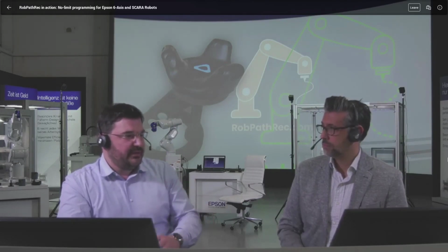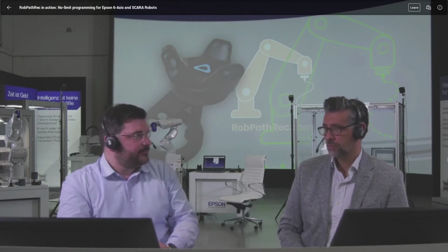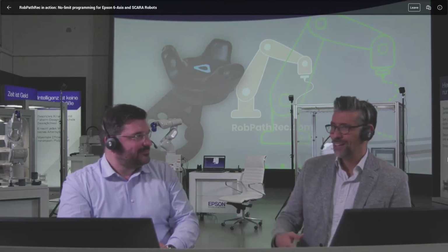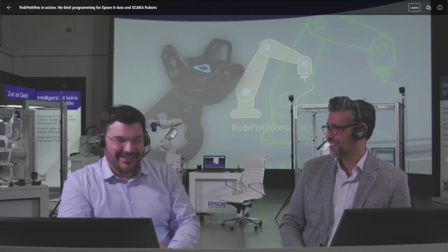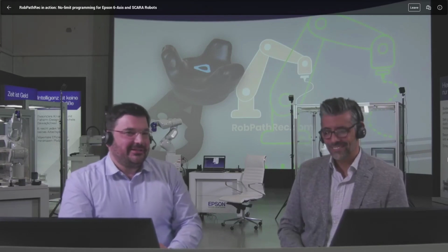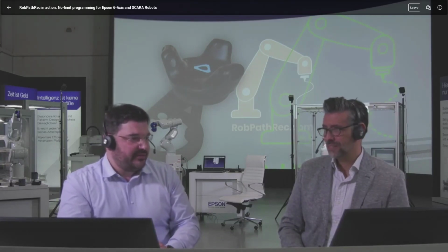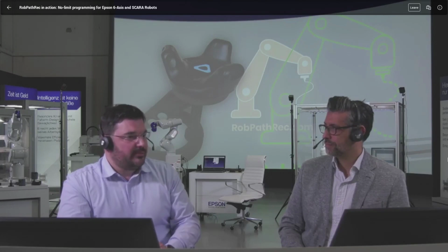Thank you. So this will lead me to another question. What accuracy could be achieved with the system? Okay, sure. We could see that even during this demonstration, we could achieve different kinds of accuracy results. So we say that approximately 2 up to 3 millimeters can be reached under any circumstances, where you are really taking care that there is no dust or any disturbing elements for the optics.